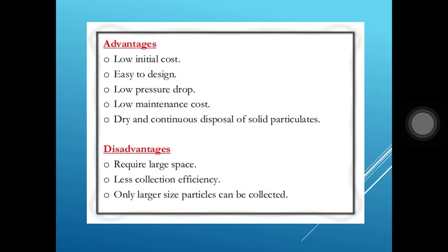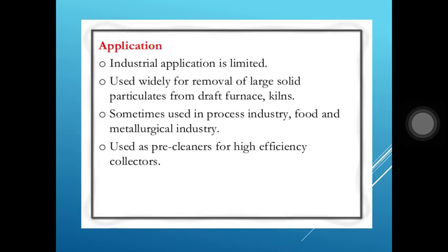The advantages are low initial cost, easy to design, low pressure drop, low maintenance cost, dry and continuous disposal of solid particulates. Disadvantages are that they require large space, have less collection efficiency, and only large size particles can be collected. Application: industrial application is limited, used widely for removal of large solid particulates from draft furnaces, kilns, etc. Sometimes used in process industry, food and metallurgical industry. Used as pre-cleaners for high efficiency collectors.